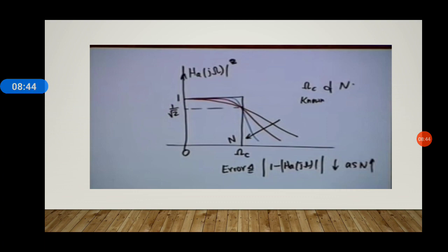So in order to design our analog low pass Butterworth filter, the two terms that we will want to know are ωc and the order n. If we know these terms, we can write the equation of the Butterworth filter.